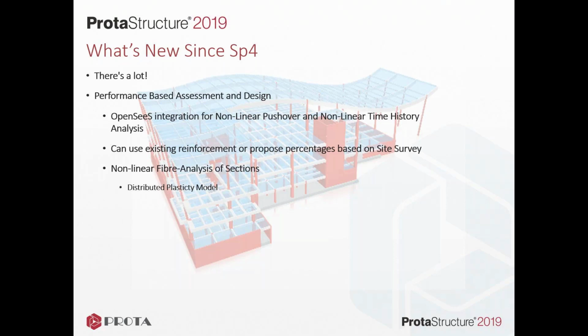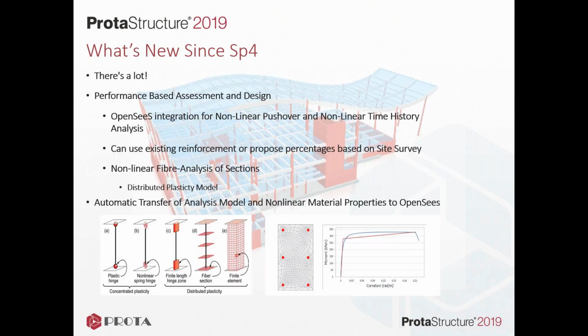You can base this on existing design that's already been done from ProtaStructure, or you can predefine steel within the model based on site survey. We use quite a sophisticated nonlinear fiber analysis model where we use distributed plasticity to create the model that we feed OpenSees. It will then carry out the performance-based design and produce a range of different reports.